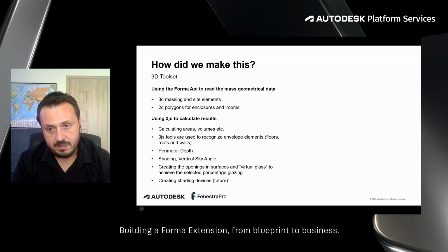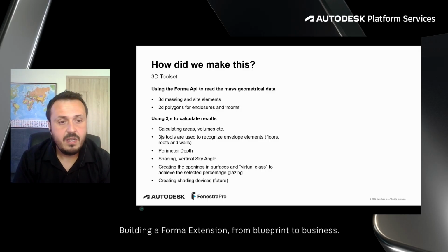But after that, that analytical opening also needs to have a host, the same as the analytical surface and other analytical elements. For that reason, we again create virtual windows. These virtual windows will have thermal properties, and at that stage we take the thermal properties of the host walls and calculate the final results for the surfaces. So at this moment, we have really valuable results that we can present to the users.